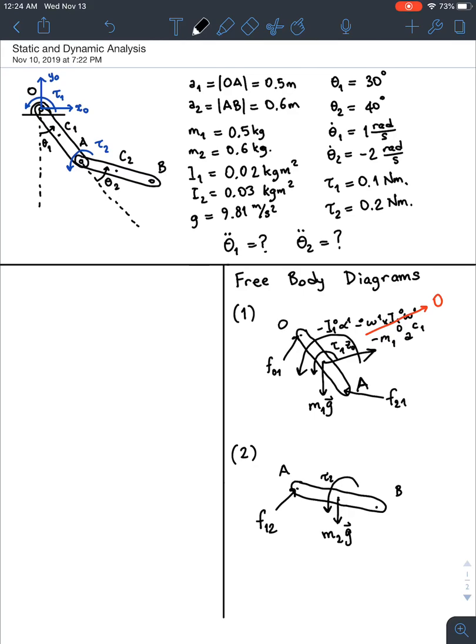these are the external forces and torques, but there are also, of course, the inertial forces and torques, as there was on the first rigid body. And the inertial force, of course, is in some direction that I don't know, so I'm just arbitrarily drawing the direction. It is minus m2 times acceleration of the point C2 in the zeroth frame. Yeah? And the inertial torque acts about the center of mass, again, and is minus the moment of inertia of the second rigid body times angular acceleration of the second rigid body minus the angular velocity of the second rigid body